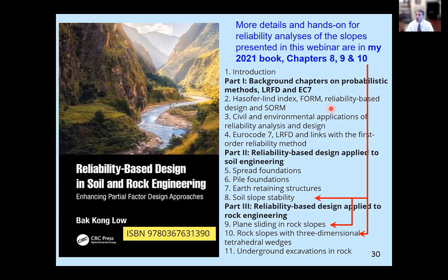Okay. Let me try to squeeze in one last quick question. You noticed in your analysis of the strength parameters, you used 1 sigma, or 1 standard deviation, off your average trend line. In Mike Duncan's 2000 paper, he uses the 3 sigma rule, or 3 standard deviations off, to get the highest likely value and the lowest likely value. Why did you choose only 1 standard deviation?